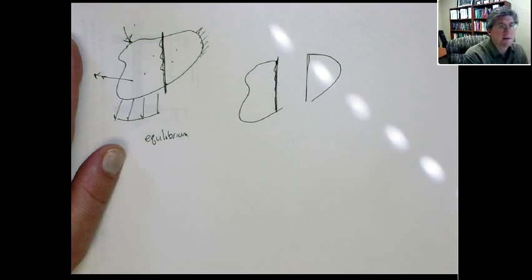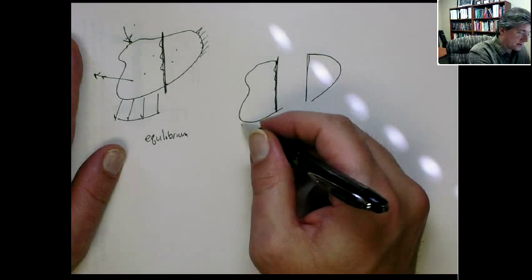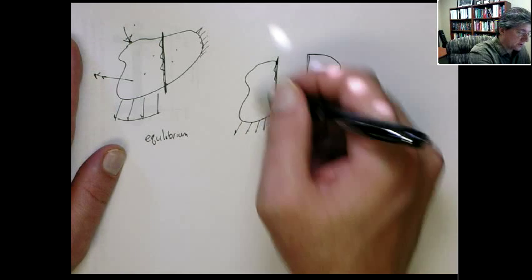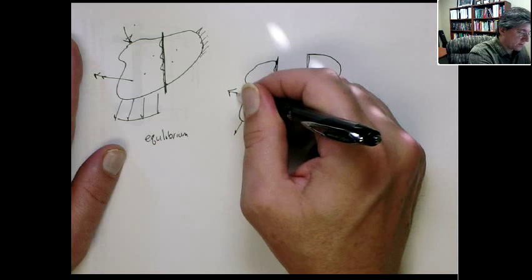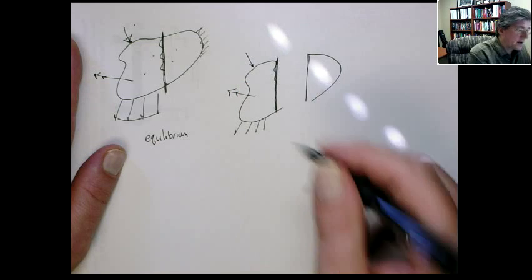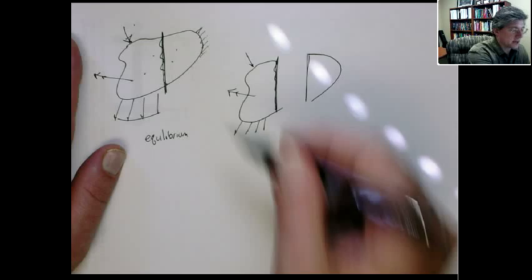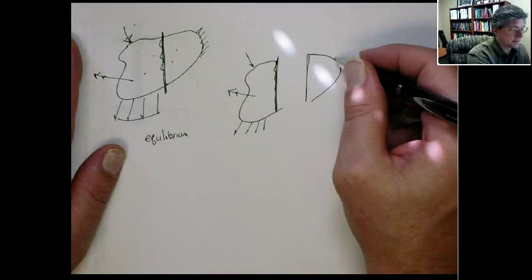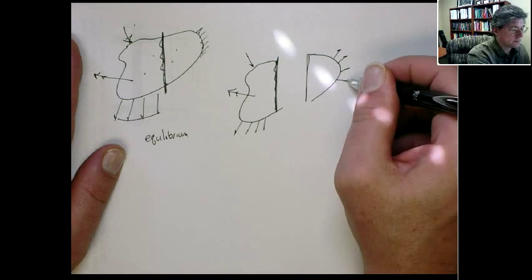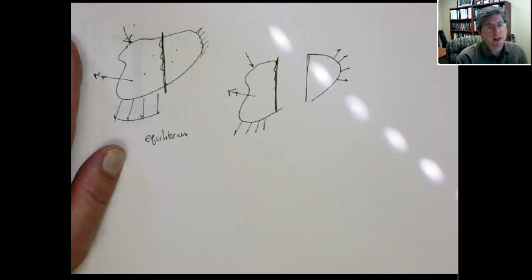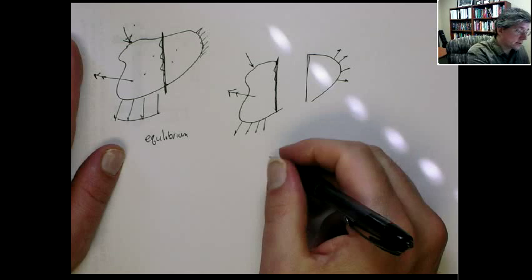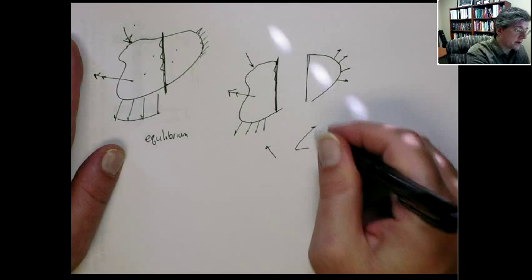It's supposed to be the same picture, but split. And here are those external forces. And now to make it a proper free body diagram, let's not put the constraints, but let's put in the reaction forces that correspond to that fixed condition. Okay? Each one of these bodies is in equilibrium.